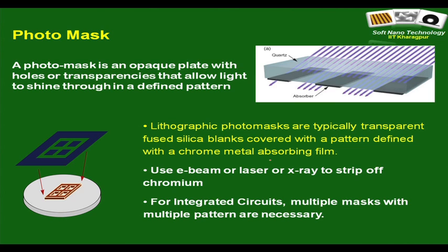In fact, a mask is a block of quartz which, at certain locations following the patterns you would like to create on your photoresist layer, is transparent to UV light, and at other locations it is opaque. So, here you can see there is a mask. In these areas it is opaque to UV light, so no light passes, and in these areas it allows the light to pass.